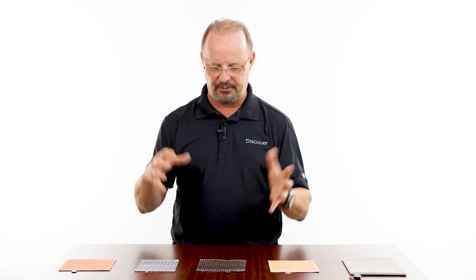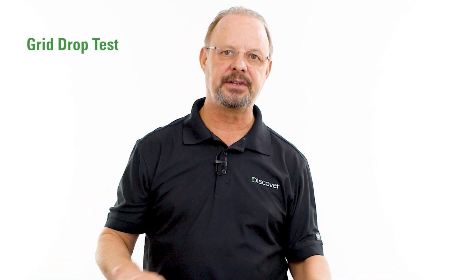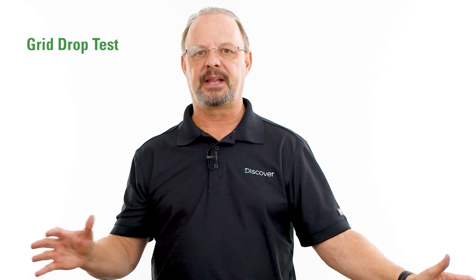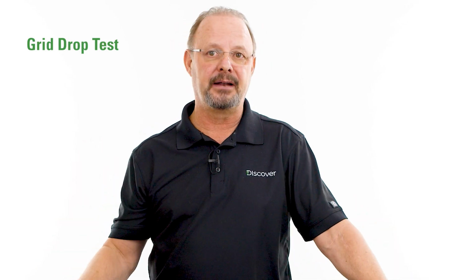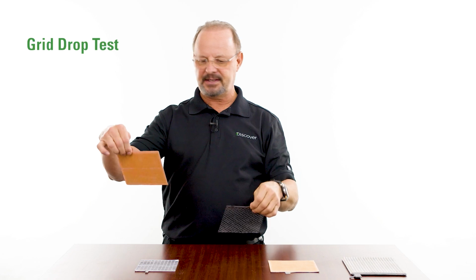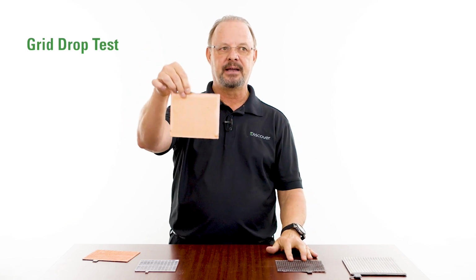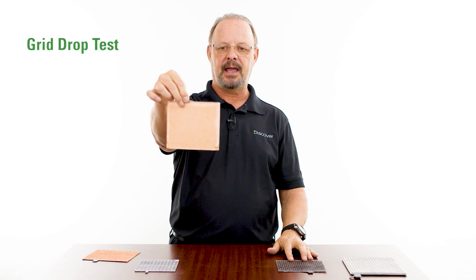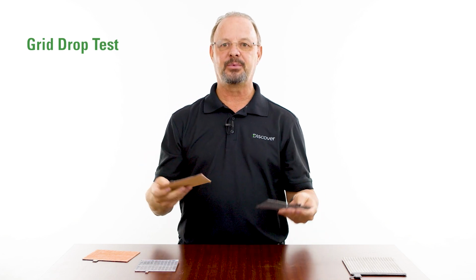When a pasted grid is cured and dried, the active material wants to shrink and generate forces at the grid wire that force the paste to separate from the grid wire. So when we talk about tensile strength and active material adhesion, and what grid design is better for active material adhesion, there are some different tests that can be done by anybody, and it's what we call a drop test. So this is a grid, and this is the same grid but pasted. We take these pasted plates, and from a height of 1 meter, we drop them. We do that 9 times. That'll show you which type of grid will hold the paste better.